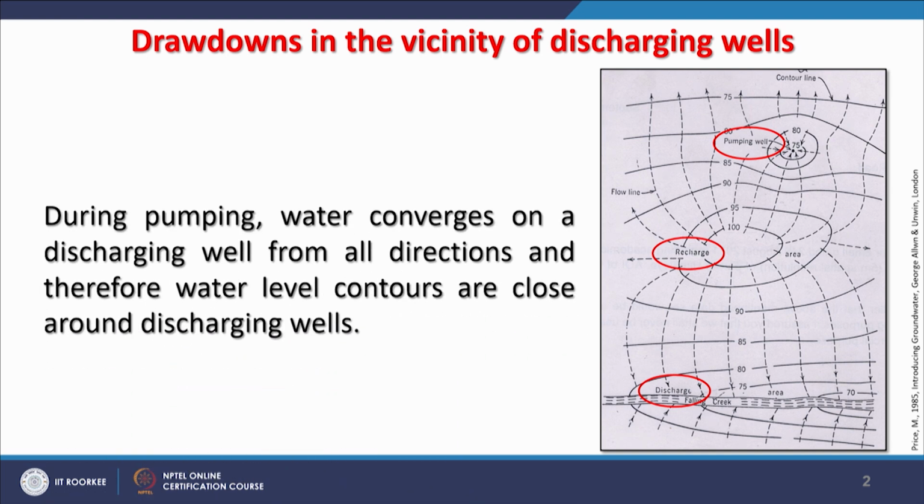and especially we are talking about the vicinity of discharging wells. The figure on the right side has now become familiar to us, so I need not explain further on this. So, we know that when pumping is happening, during pumping water converges to a discharging well from all directions, if geologic conditions are like that.